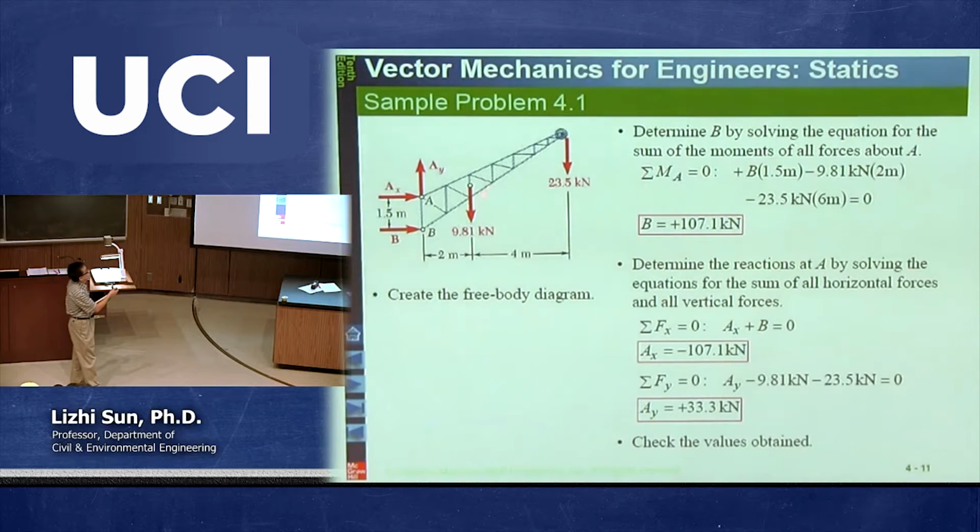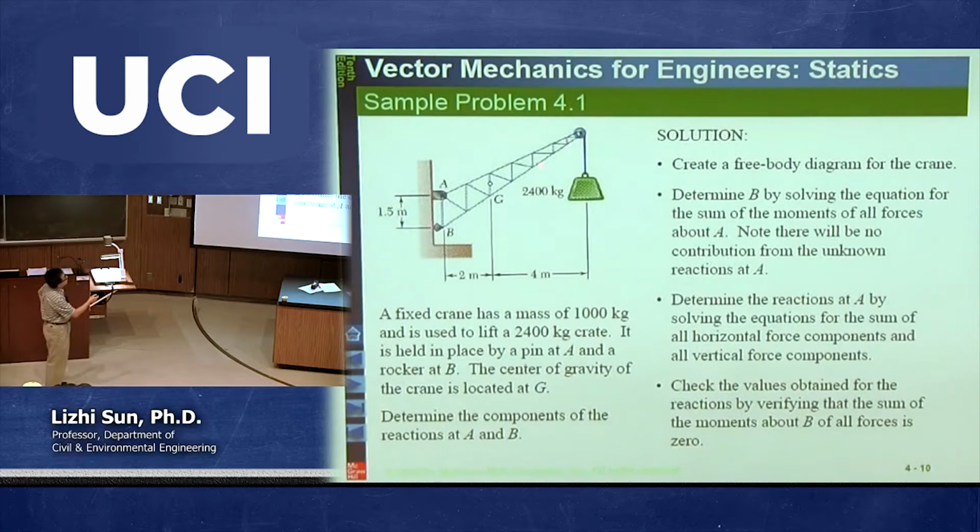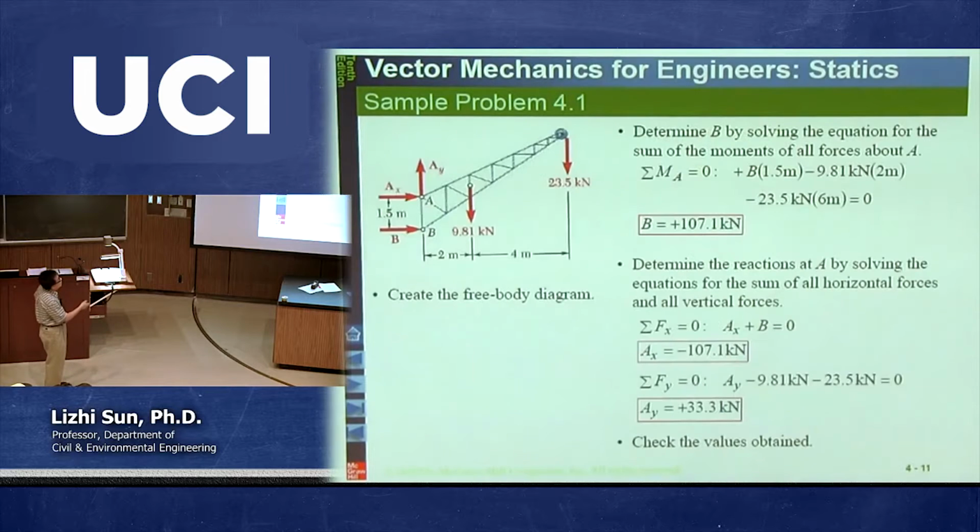That's the self-weight of this crane. Okay? Let's go back to look at this again. This rigid body is also interacting with this wall, which is the outside world, at point A. So then we cut point A. When we cut point A, we realize this is a pin. When we cut point A, which is a pin, then we need to plot two reactions. So these are the two reactions representing the pin support.